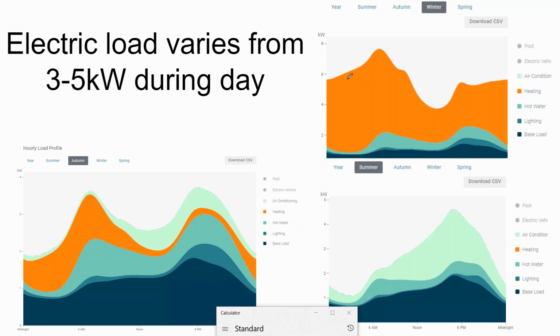So kind of the goal in off-grid design is when you're picking your appliances, try and have this load profile be as flat as possible. Or if you're wanting to go the next step, to have an intelligent smart home that can kind of surge up and down with your solar array production.